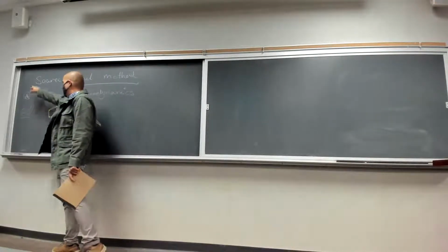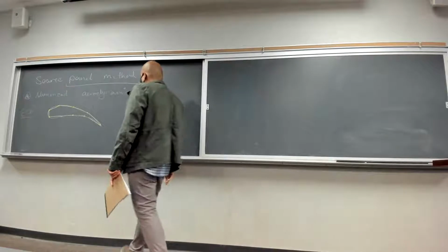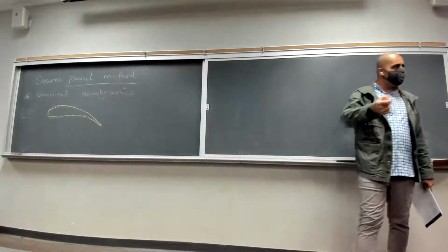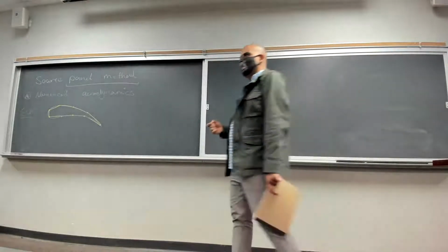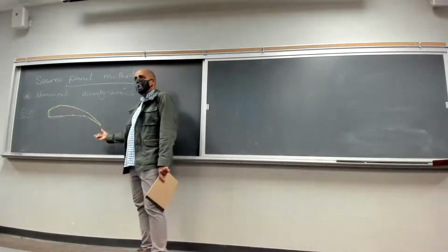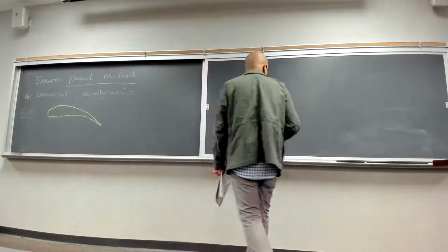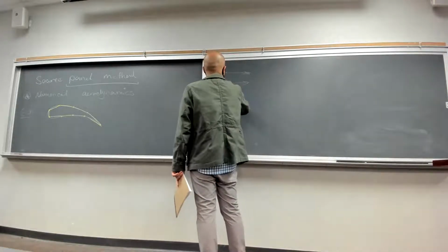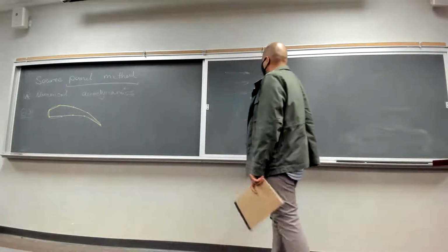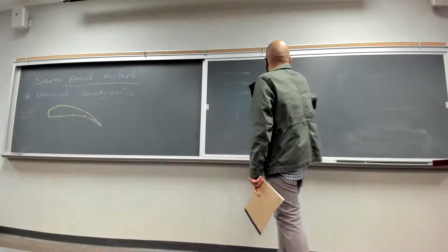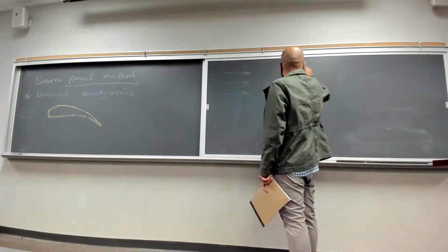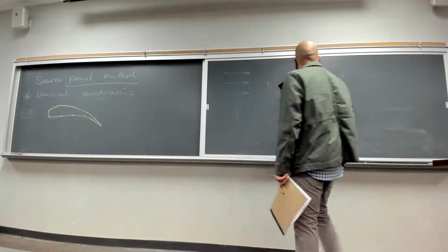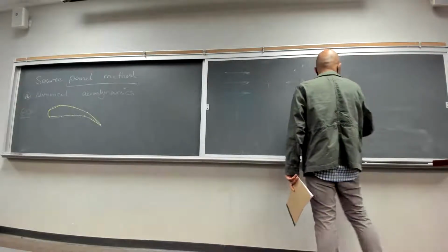But what does this source panel method mean? Source at the beginning essentially means that we are going to use the concept of source flow to solve the problem here. So, how can we do that? Let's go back to an earlier discussion we had. We added a potential flow, a uniform flow, plus a source flow to build this type of more complex flow.